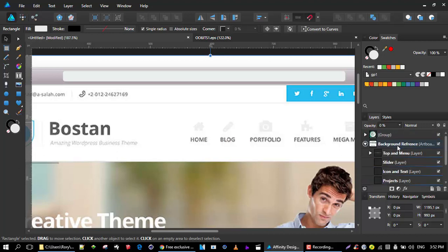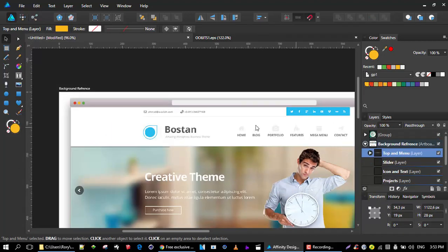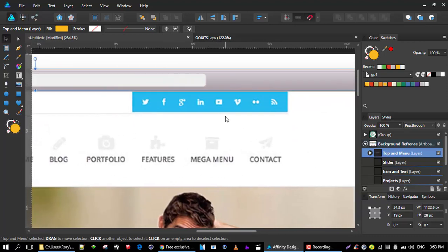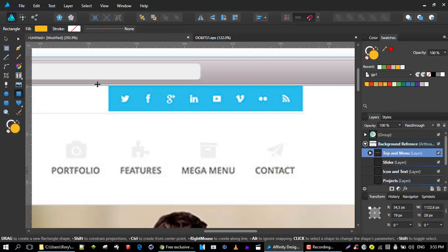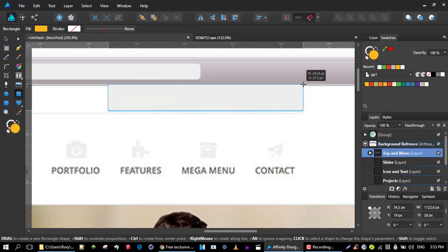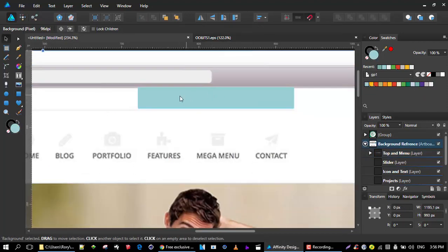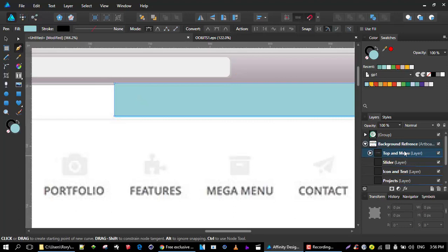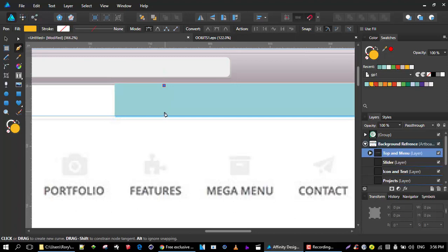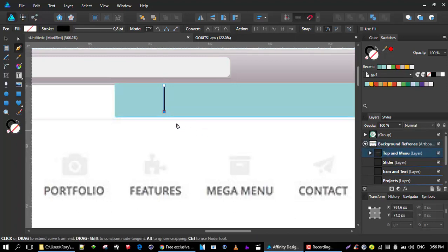Okay, next we've got to make sure that we are on that layer before we start doing anything else. So we'll come here to this particular text box. Same thing applies. We're on the layer, making sure of that. Go and select. Oops, we've made a move there. Wrong selection. There we go. So we put that block in there. Okay, so in this case now I'm going to have that, and I just want to make sure I'm on the layer still, single lines. Click there, keep Shift to constrain, click there.